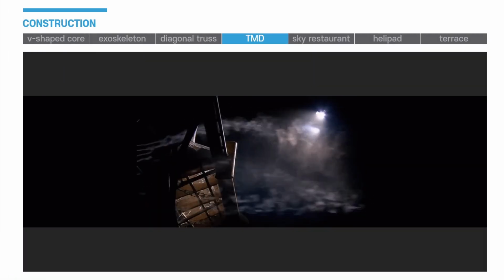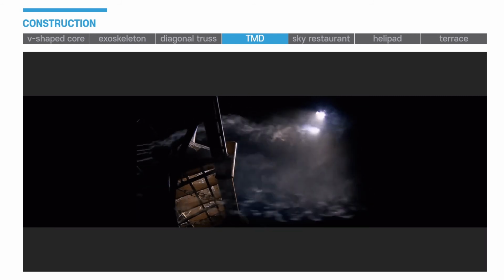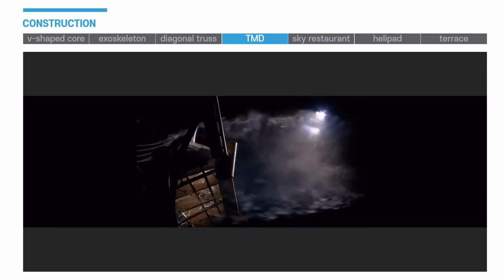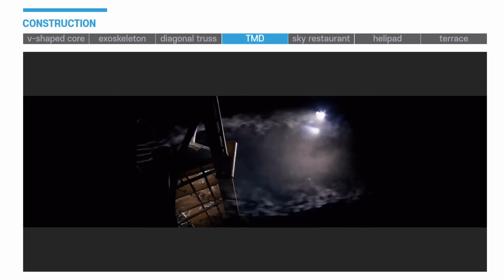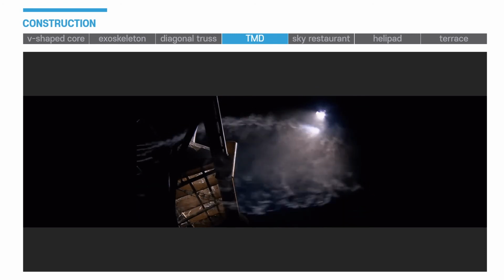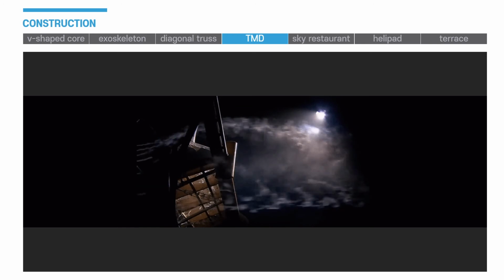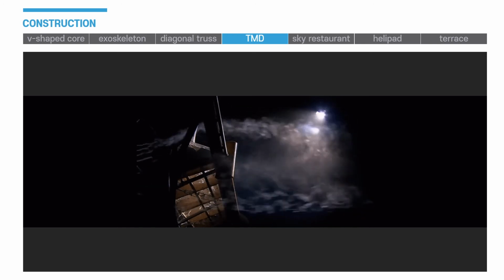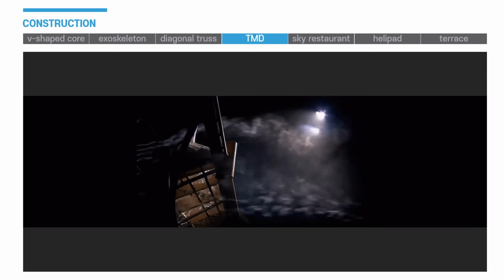The wind tunnel simulates the wind effects of the Gulf around a 1:50 scale model. Certain wind conditions blowing over sharp edges on the steel structure created miniature tornadoes which could result in dangerous vibrations, causing the building to be destroyed. By this wind tunnel test, the aerodynamicists searched for a way to handle this vortex vibration.